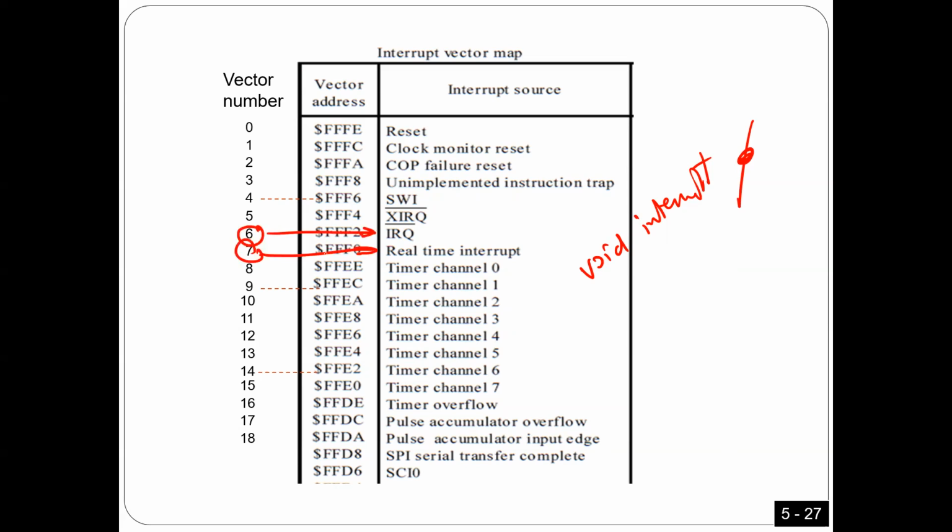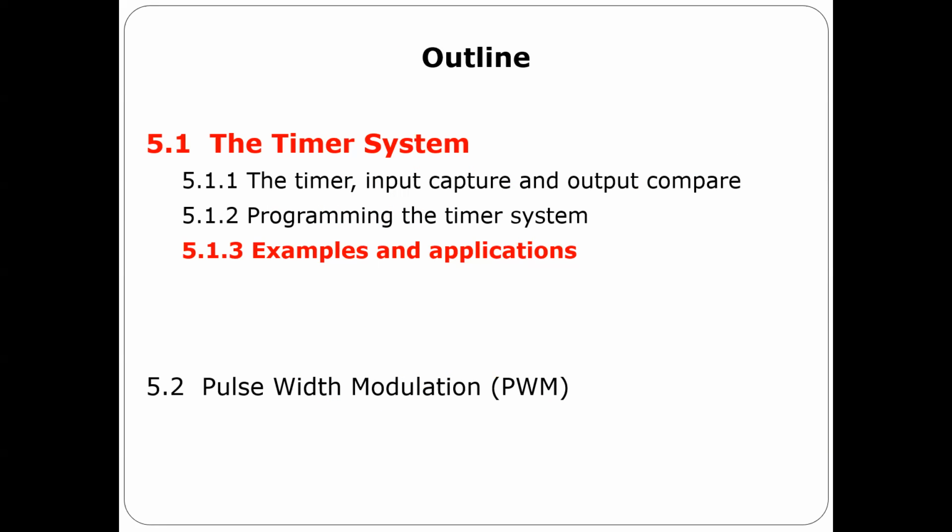Same thing here. So here, in case of a channel 0, you have to use number 8, number 9, number 10. That's it. Is that okay? Just change the number to tell what this interrupt is for. Is that easy? Similar to what we did before. The only difference is before we just used 6 and 7. Now you have to use the correct number here based on what interrupt you are programming. Any questions? Okay, guys.